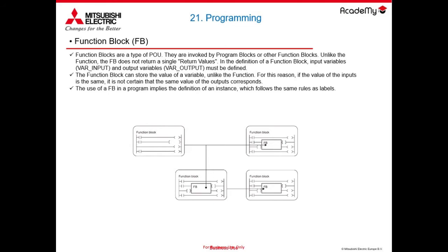In the most generic case possible, where you have to interface in a program logic with n electrical axes of the same type, you can think of encapsulating, therefore building a program logic that manages all the electrical axes present on our machine. The logic is written only once, an FB is created. N instances will be created and added to the project, as many as the axes we would like.